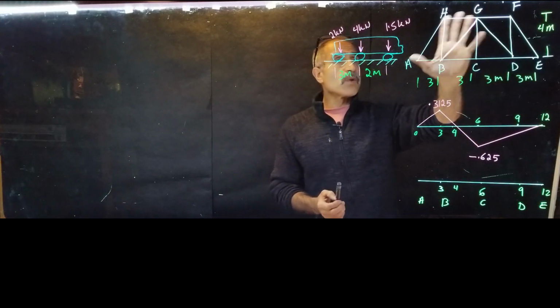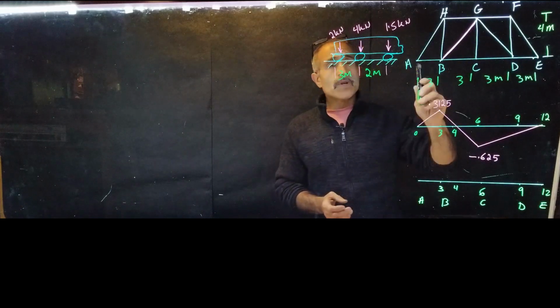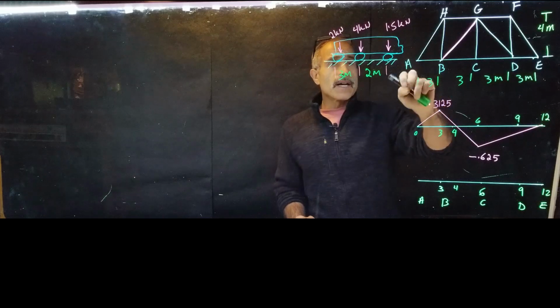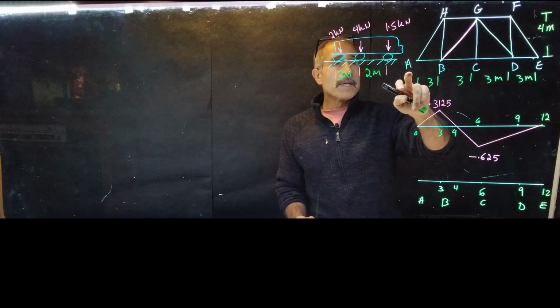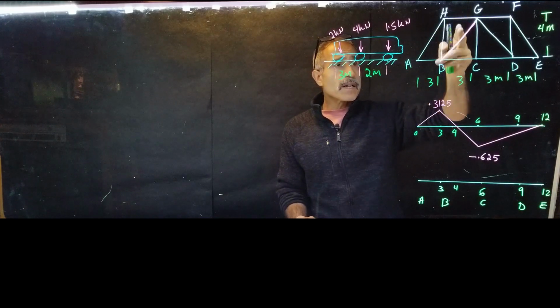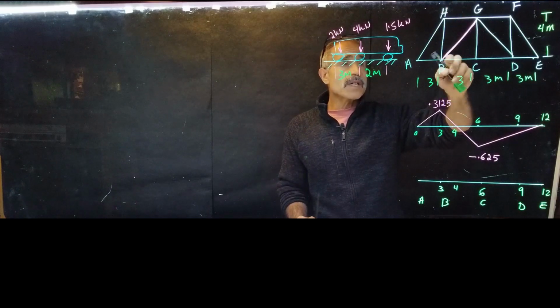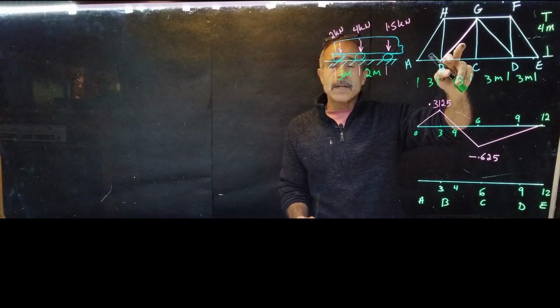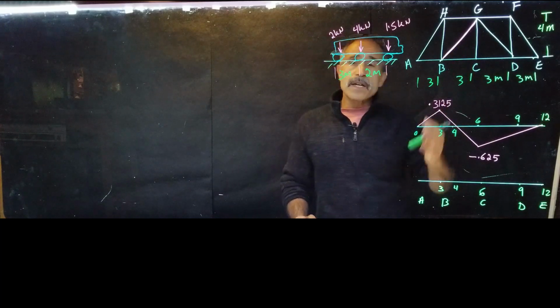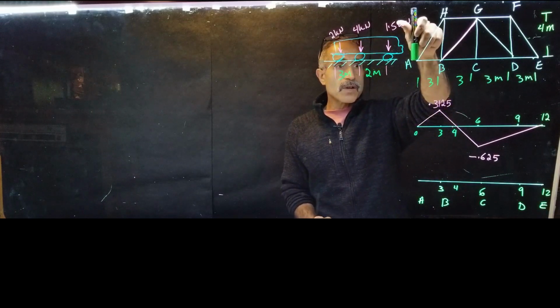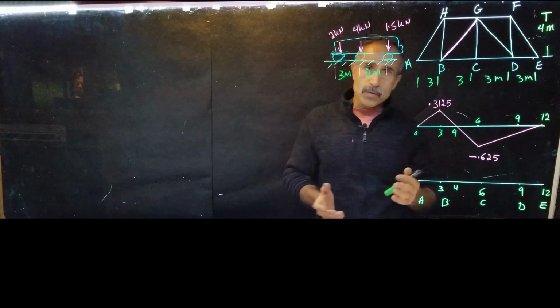If we take a look at this whole truss and load it with a 1 unit load, I put the 1 unit load here and calculate AY. Then I cut the truss in half, use the method of sections, and calculate the member force in BG. Then I write it down, and that becomes 0. When the load is at that point, the member force comes out 0.